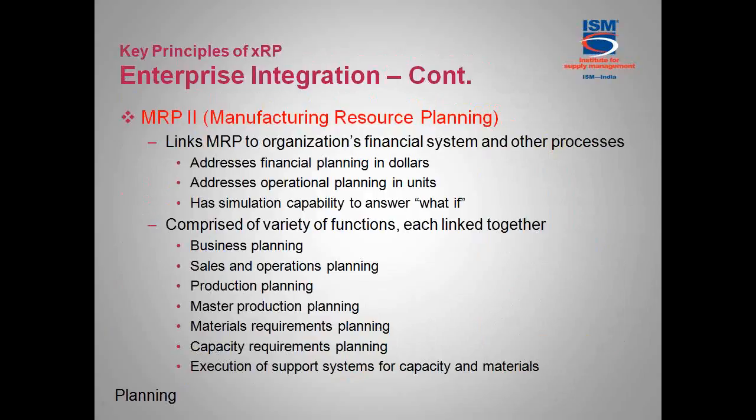Now, when we are doing the MRP process, the capacity process is also required, which is called capacity requirement planning. At MRP we are talking about which particular material is required. At capacity requirement planning we are talking about what is the available capacity at a particular work center, what is the required capacity, and what is the load profile on various machines.